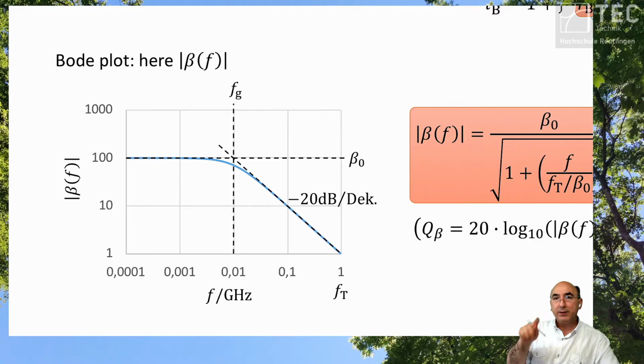My integrated circuits using silicon germanium to make 24 gigahertz amplifiers have had transistors which had 50 gigahertz transit frequency.